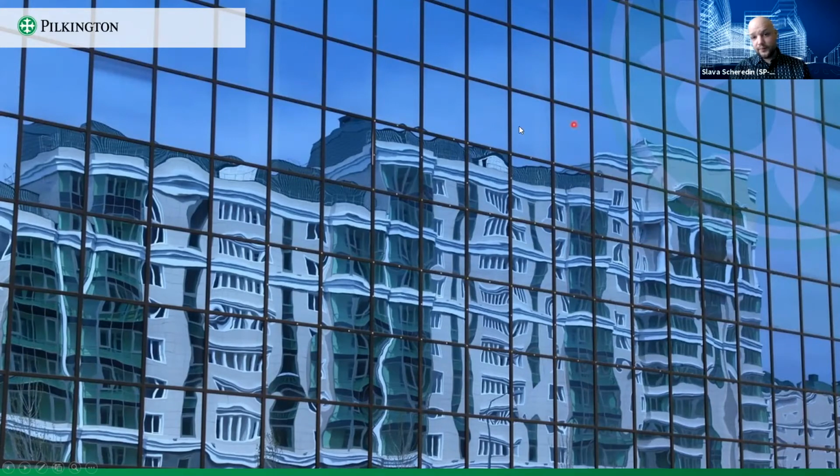But on the top, IG units are close to ideal. Are they different from the bottom ones? The answer is no. The difference is just in the photo, because the bottom ones are reflecting something of geometrical shape, meaning the opposite building, and the top ones are reflecting nothing, just a clear blue sky.